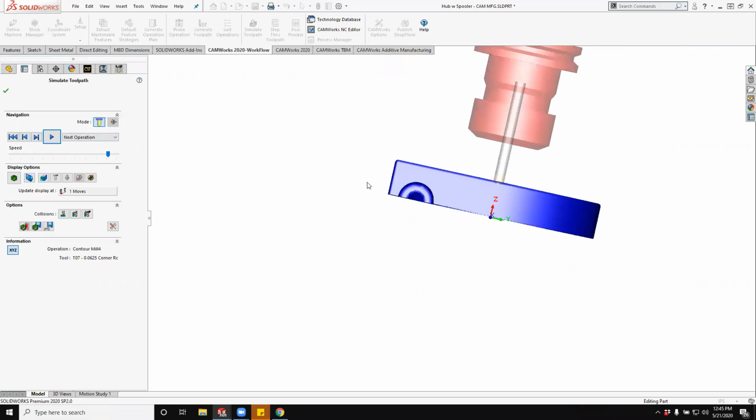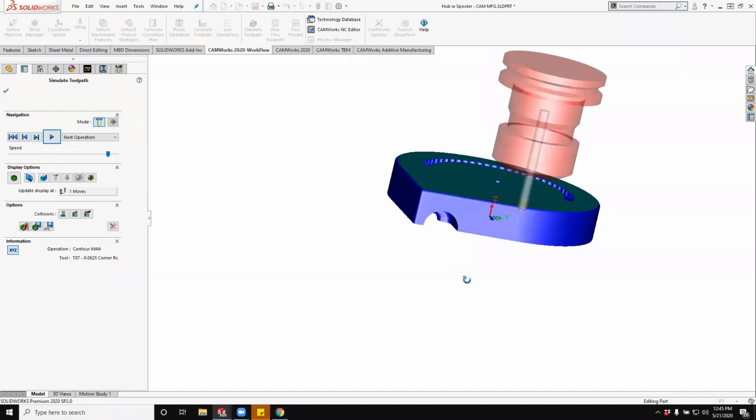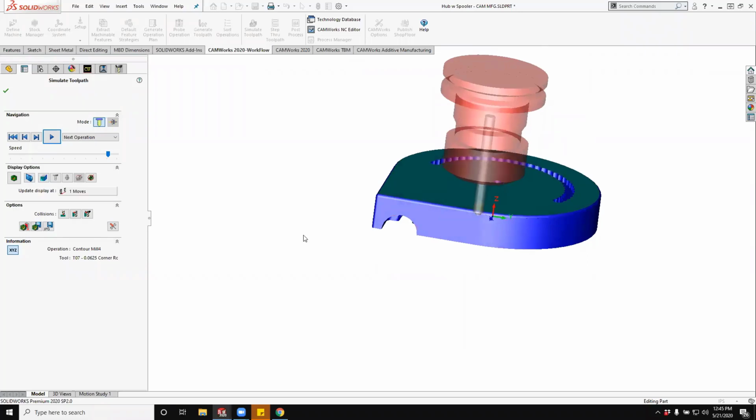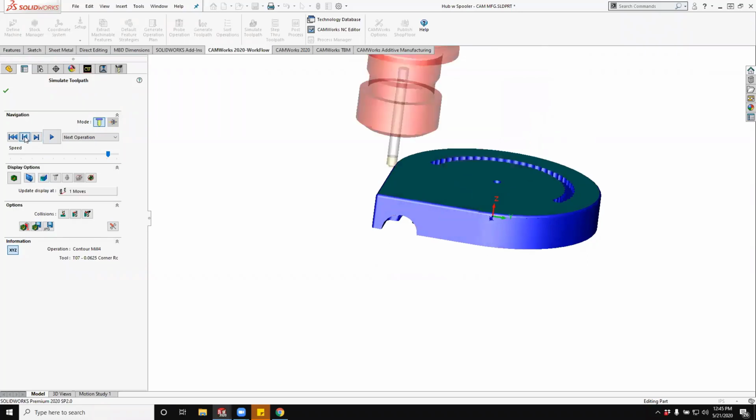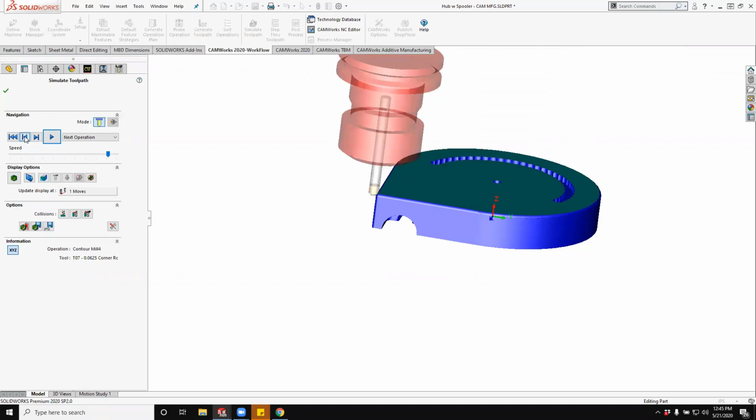That's why we call it 2.5 axis, because we set the z, that's kind of our half axis, in a stable, set plane, and then we're moving the axes around and we see x and y axis movement. We've got to be moving those simultaneously to create this feature. And so that's a 2.5 axis operation.